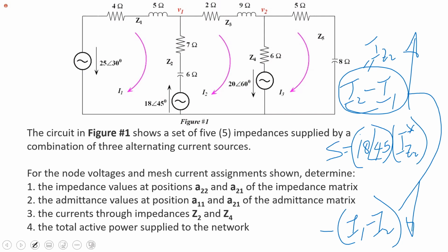Sir, to sum it up then, when the current is entering the source, you change the sign, so you make it negative. Folks, to sum it up, it's the same thing that we talked about in Networks 1, about supplying power and absorbing power. We said that it is supplying when the current is leaving the positive side. We have not changed anything; all we have done is migrate from resistive-only networks to putting in some inductance and capacitance.